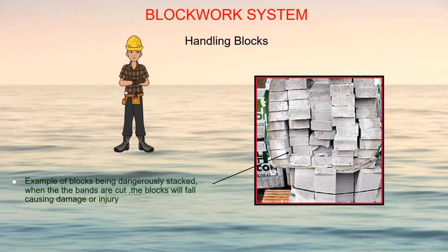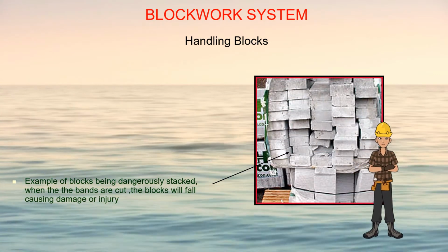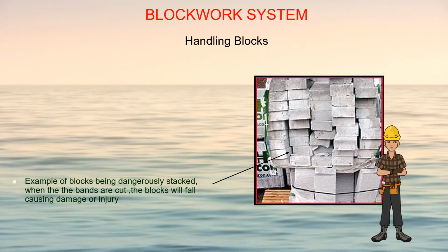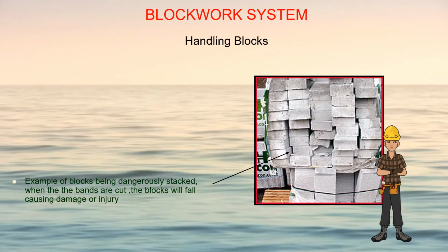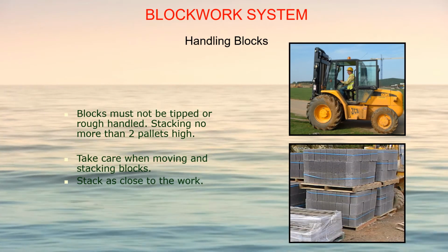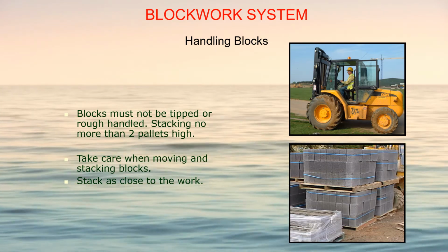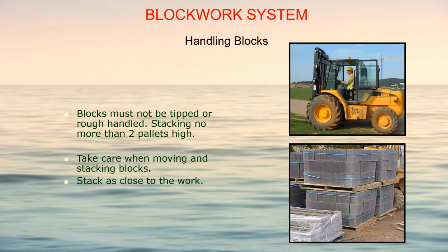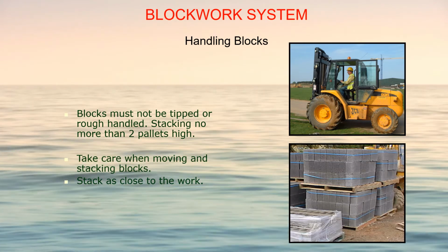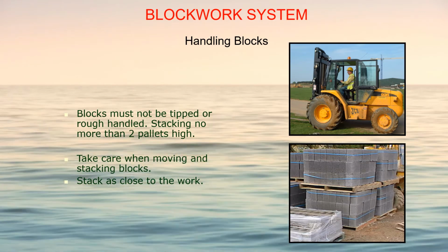Blocks are usually delivered on pallets and should be stored on a hard level base or on battens on drained, even ground. Blocks must not be tipped or rough-handled. Move blocks in packs by mechanical means, stacking no more than 2 pallets high. Take good care when moving and stacking blocks ready for use.